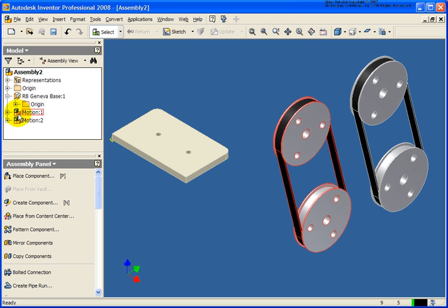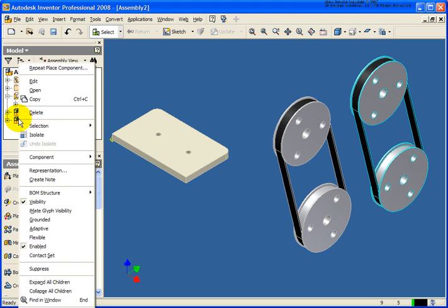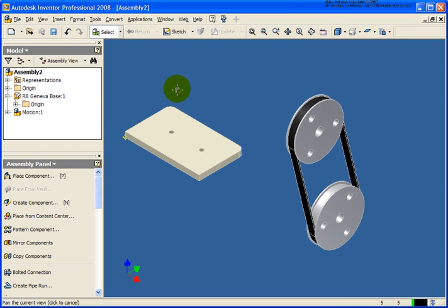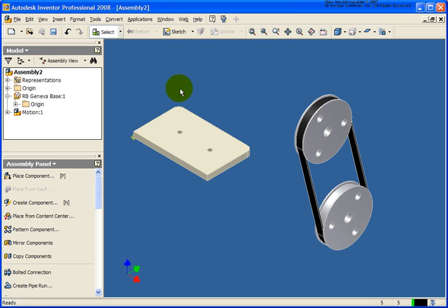In this case, you'll see that there are 3 blocks representing that. It's showing me that that's the assembly, and by expanding that, you can see that I now have 3 individual components nested inside there. So again, I'm going to delete motion 2 because I don't need that, just like we did before. So that's all there really is to placing existing components into an assembly file.